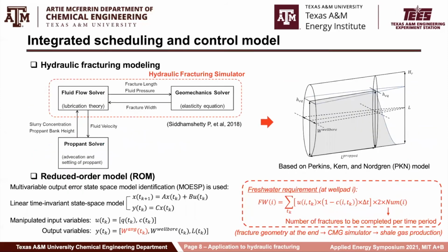To formulate the integrated scheduling and control model in the outer loop, we first develop a reduced order model for hydraulic fracturing. In this study, the utilized high fidelity process model is developed by Prashant in our group, with which we are able to obtain the temporal evolution of the fracture lengths and fracture widths at different locations. Using the simulation data generated by this high fidelity model, the MOESP technique is utilized for model identification.